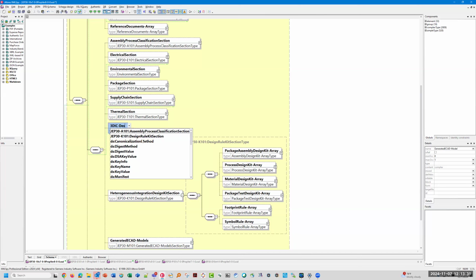Okay. The reason I asked Tony, maybe you're more involved in this than I am, but at least when I hear the terms, to me, heterogeneous integration seems to be a little bit narrower in scope, but maybe that's not really true. It seems to me like heterogeneous integration refers to what the defense agency is trying to do, but not only the defense agency, any group that's trying to collect chiplets that use different process technologies and integrate them together onto the same 3D package.